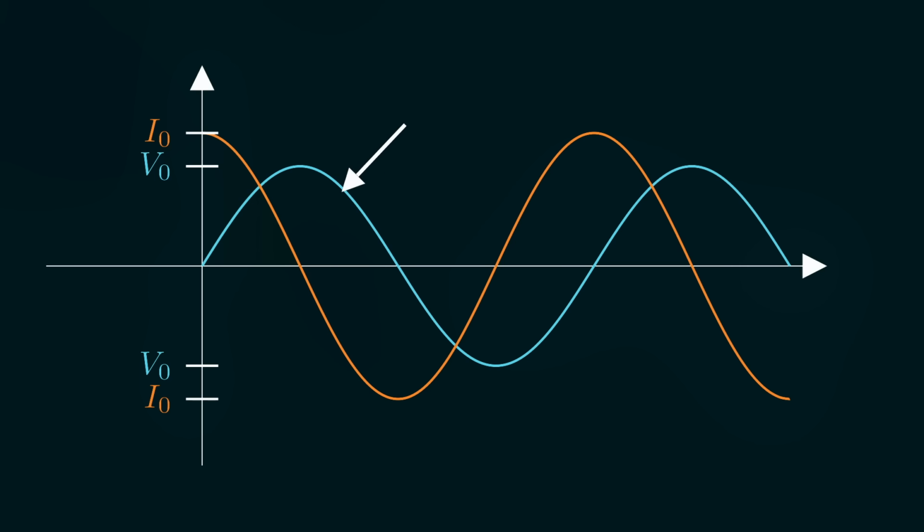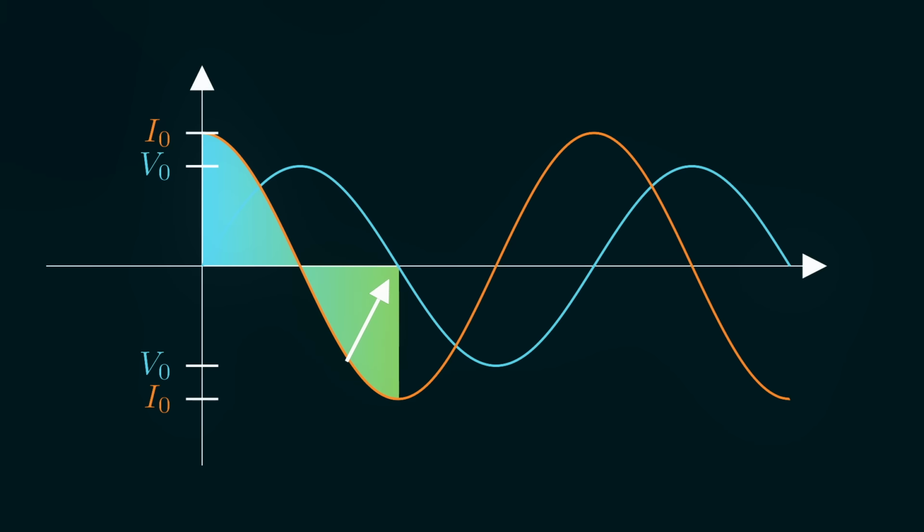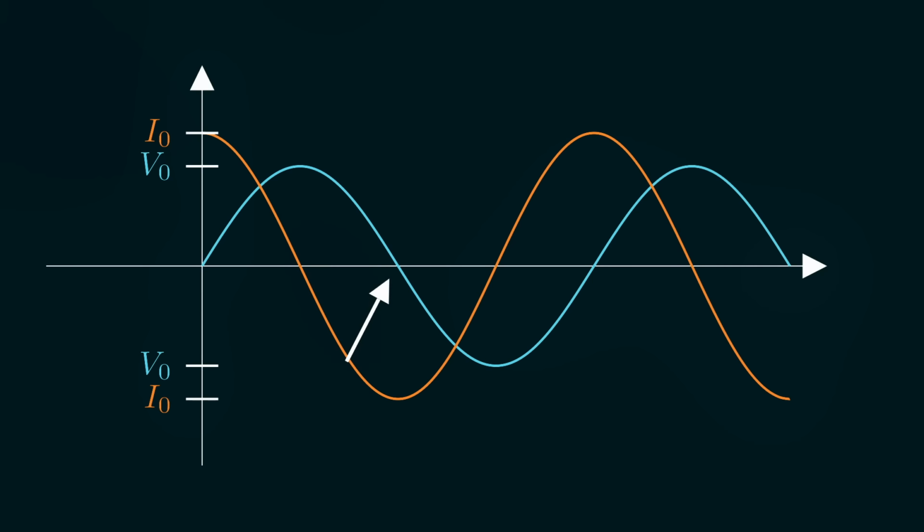Now when you start decreasing the voltage, the capacitor has excess charge on it, so to get rid of it, it's going to start discharging by sending current in the opposite direction, which is where we get the negative current from. And it'll keep discharging more and more until the voltage reaches 0. At this point, the areas under the curves cancel, which means that there's no charge on the capacitor right now. So when the voltage starts going negative, it's going to act like a wire again, quickly drawing lots of current, except now it's in the opposite direction. And now we have the same cycle repeating, but for negative charge and negative current.